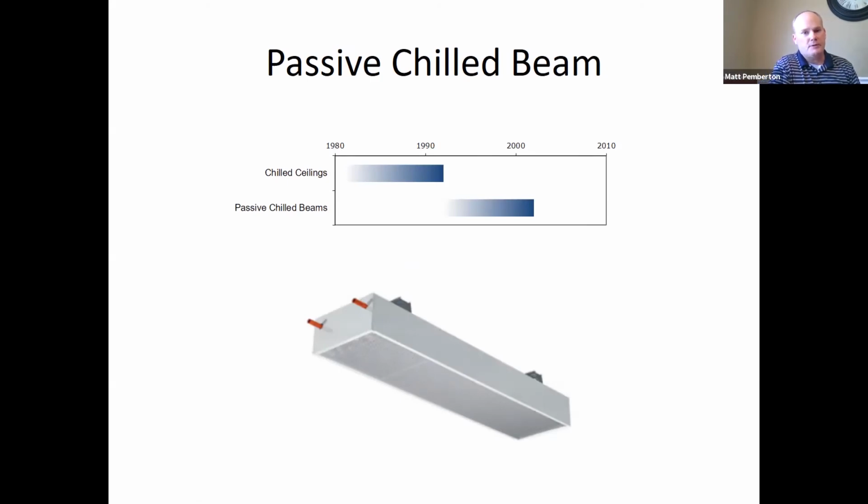Where these are typically 10, 12 feet from the floor, just to give you an idea of floor to beam height. It's not necessarily floor to ceiling height because we can have higher ceilings and just pendant style, hang the beams down from wire, whatever you may do in your space, all thread, something that would look nice. But the large majority of the cooling coming from the passive beam is through convection.